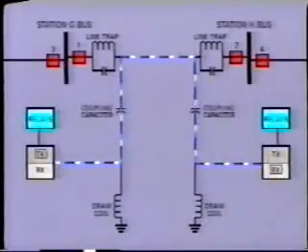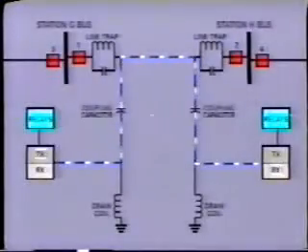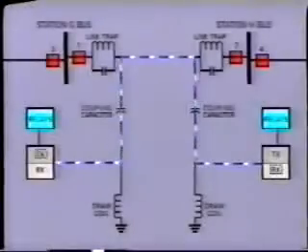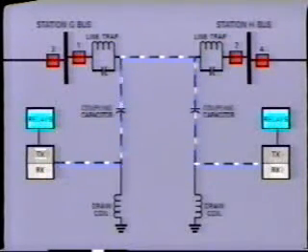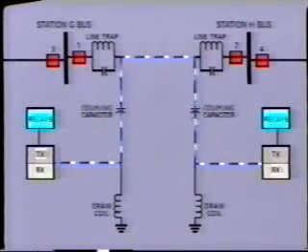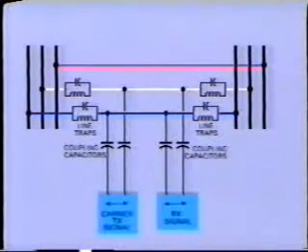The signal current circulates through the power conductor, out to be captured by the receiver through the coupling capacitor at the far end. This is where only one power line conductor and ground is used to conduct the carrier signal. An alternative scheme may use a phase-to-phase connection. As shown in this schematic, the transmitter and receiver are coupled to two power line conductors at each end.